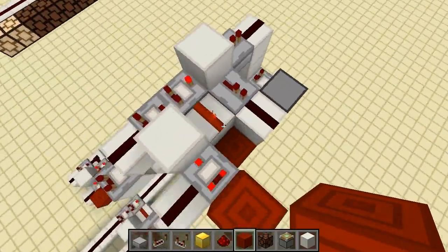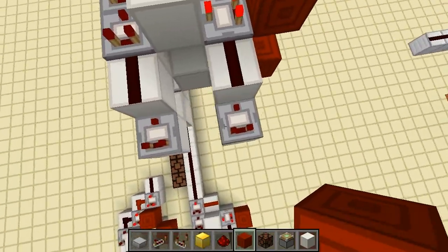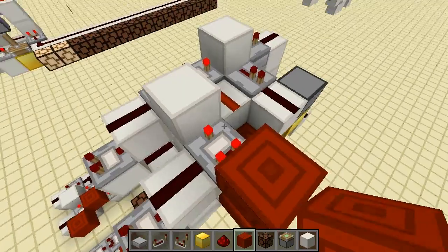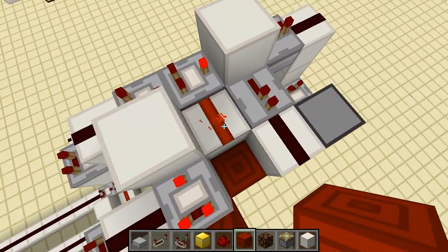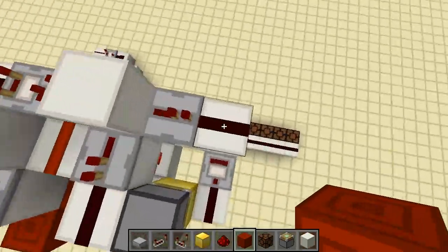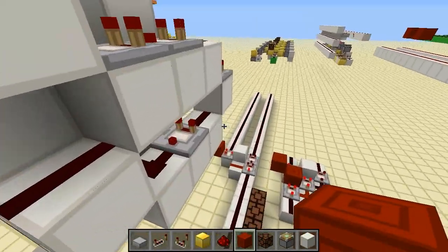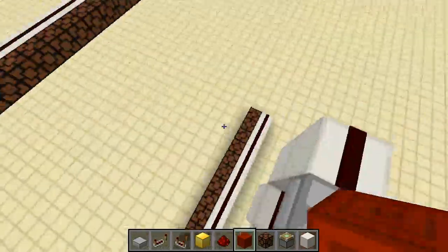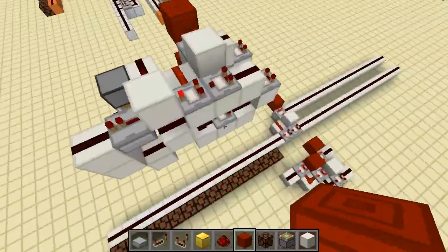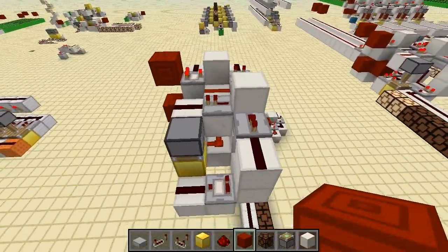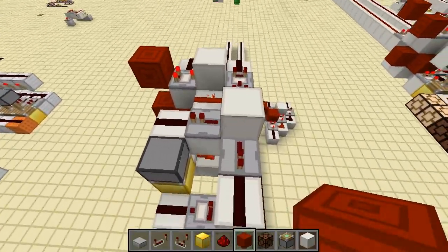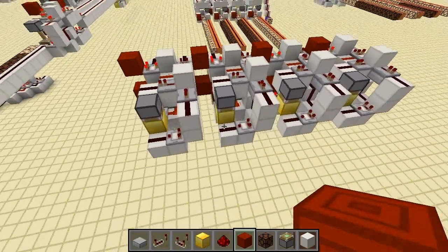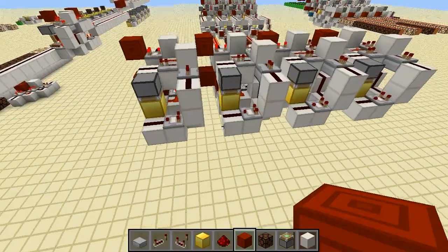And the full adder takes into account a third variable, because here we have 2 variables, input A and input B for this digit. The full adder takes a carry in. Like this has a carry out, whenever we have more than one digit, the second digit will have to take the carry out from this adder, which will be the carry in from the next. So we're going to just go and stack some of these half adders up and then make the full addition logic. Here we go, some nicely pre-stacked half adders. You'd almost think I'd done this before. Actually, I have, several times.